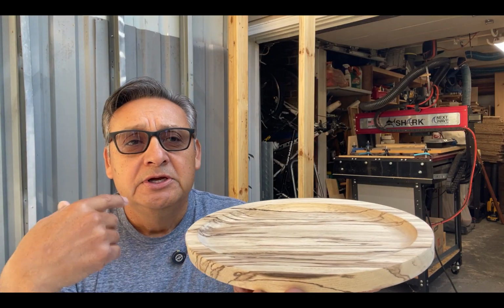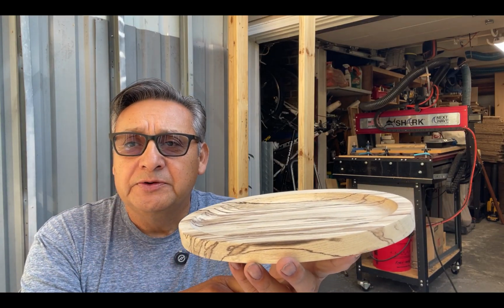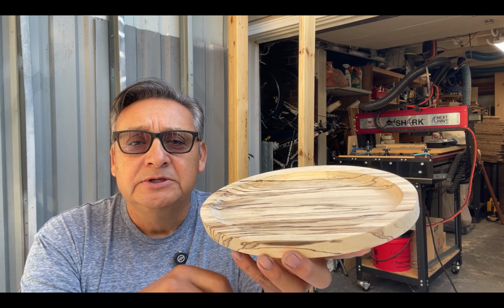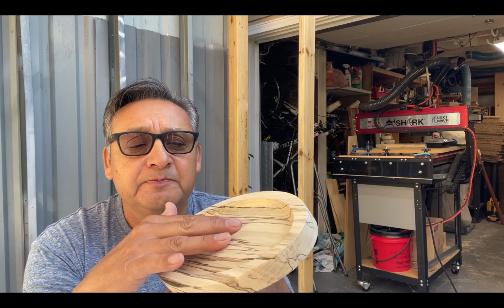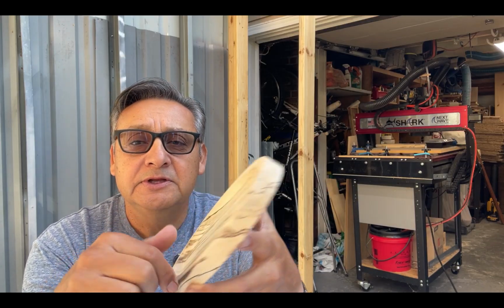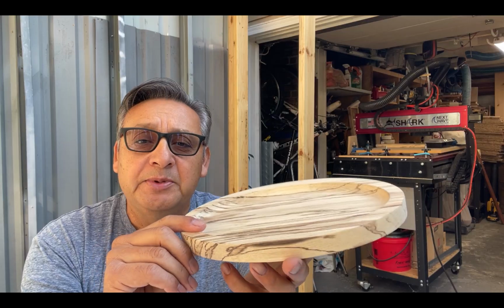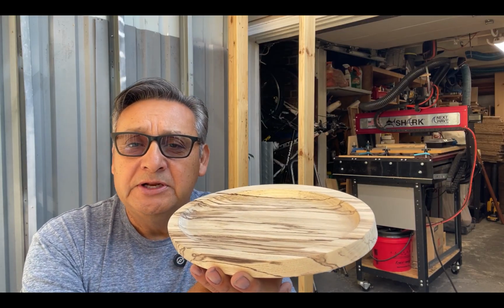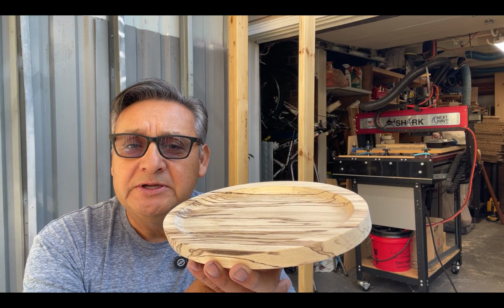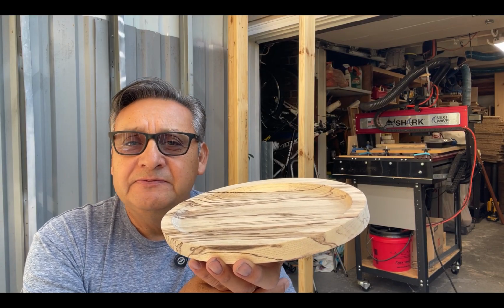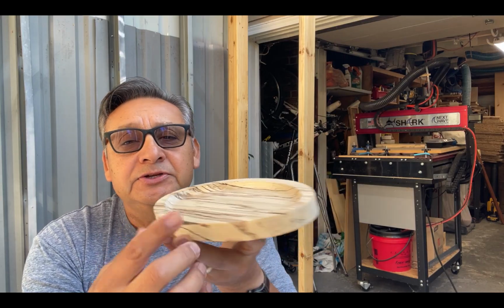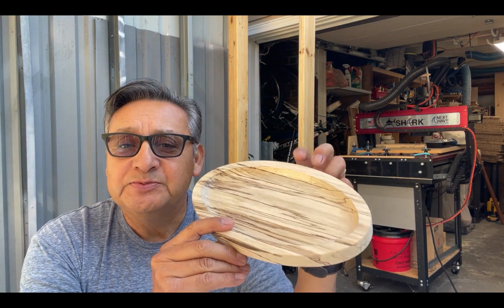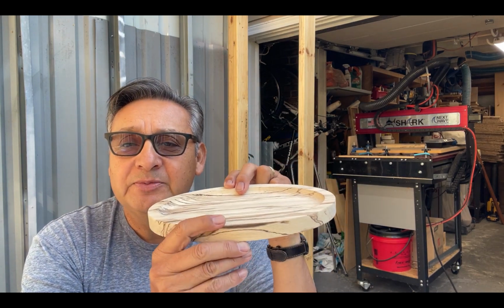And so in this one we used a 3/4 inch bowl bit, and we used the 1/4 inch end mill. So the bowl bit obviously cut out the interior, and the end mill did the profile. But the big difference is, in order to cut out the pocket with the bowl bit, it only took us just under 5 minutes. So about 4 minutes and 48 seconds. All right, and to do the profile took about 2 minutes. So in its entirety, cutting out this bowl or this tray took 7 minutes.